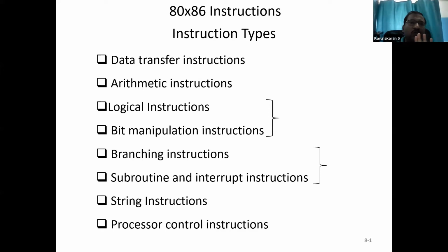Now shifting it one more time, 0100, it is 4. Shifting again, 1000, then it is 8. So by shifting only one bit, in a fraction of microseconds I can double it. Similarly, if I shift to the right side, 1000 will become 0100. It will reduce to half.